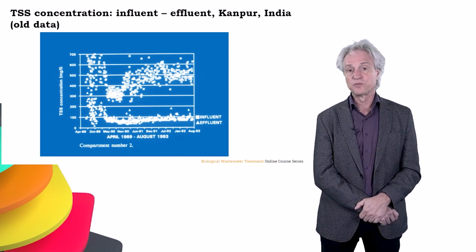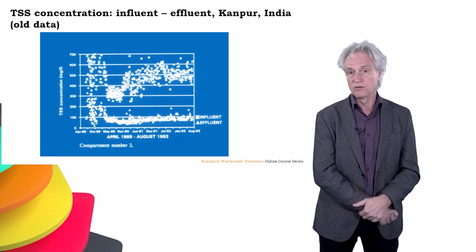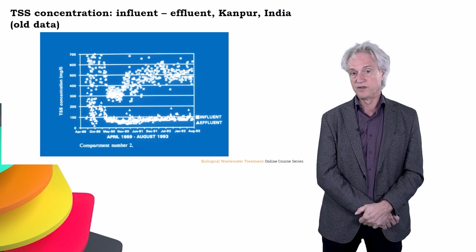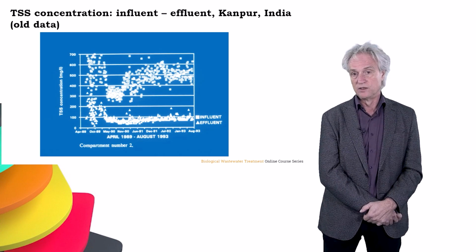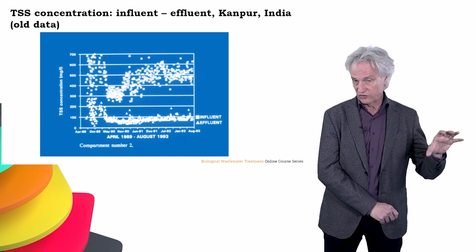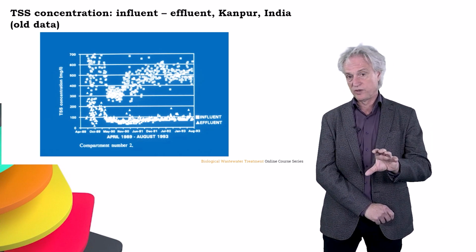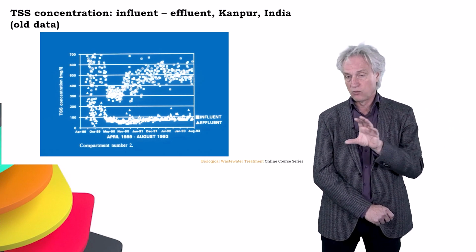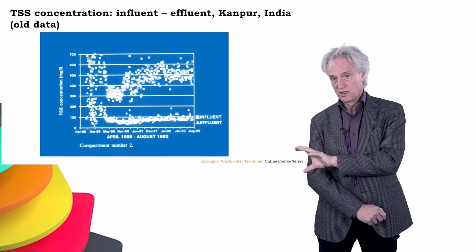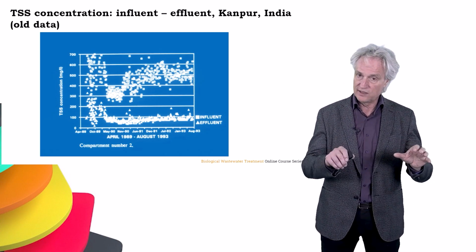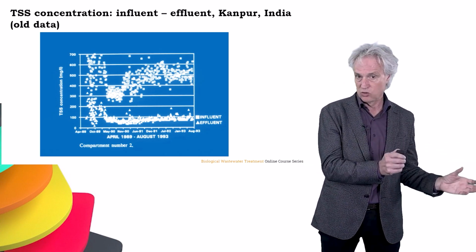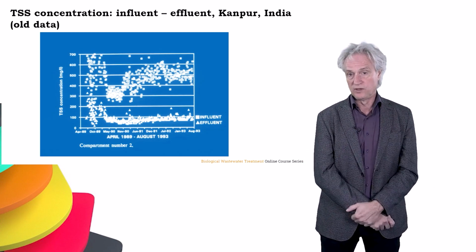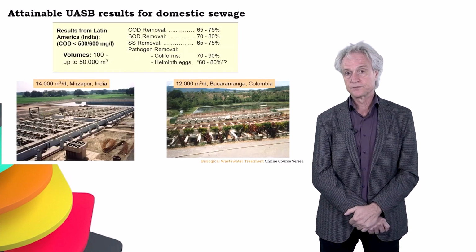Now in the end, the suspended solids varied around 500 milligram per liter, and in the effluent it was a little bit less than 100 milligram per liter. So the bulk of the pollution is taken away by the anaerobic reactor. But you also see that the effluent values are relatively high. So you do need a post-treatment step. You do need an integrated approach of an anaerobic reactor and a post-treatment reactor to arrive at the legislative criteria.